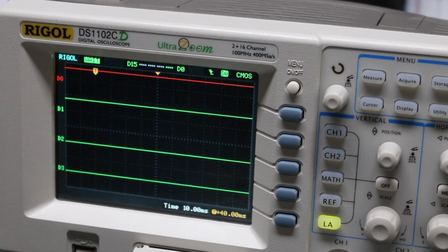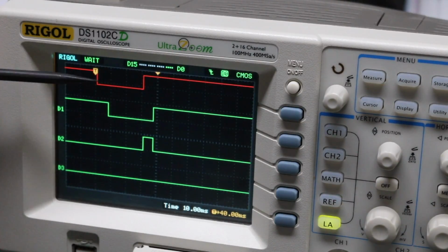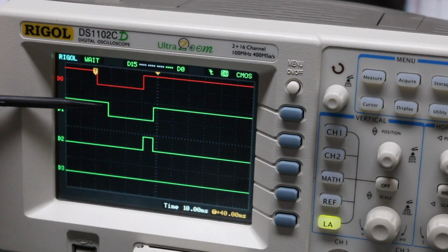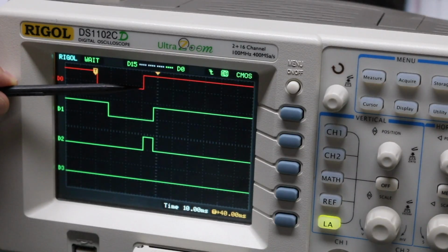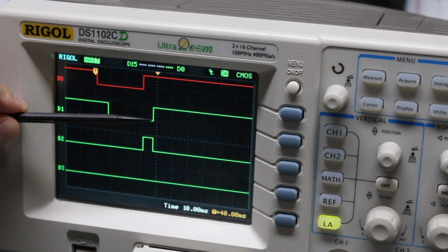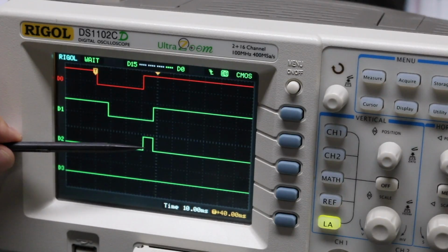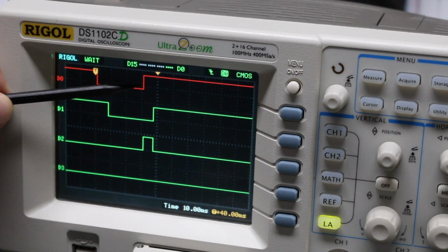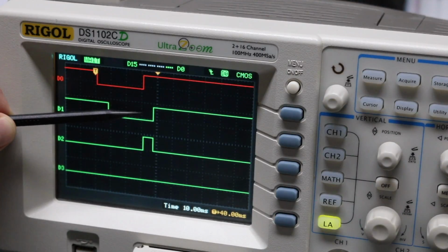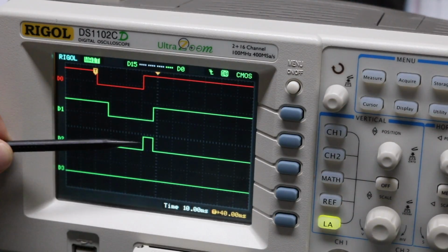I zoomed in, so I'm going to try capturing 1 clockwise rotation and see if we can analyze it. So, going clockwise, A went low first, then B went low, and then as the disk was rotated, eventually A was released and went pulling high, and then B was released pulling high, and we get a clockwise output. So we can see the output pulse is being generated in the time between one of the inputs returning to high and the other input returning to high. That's how wide the trigger output pulse is.